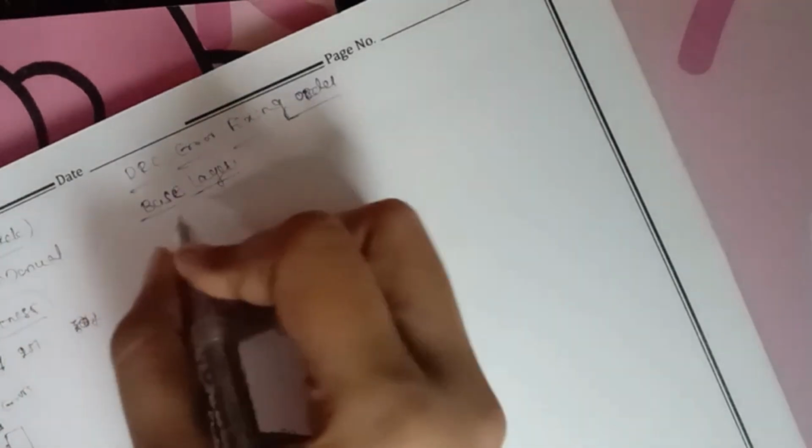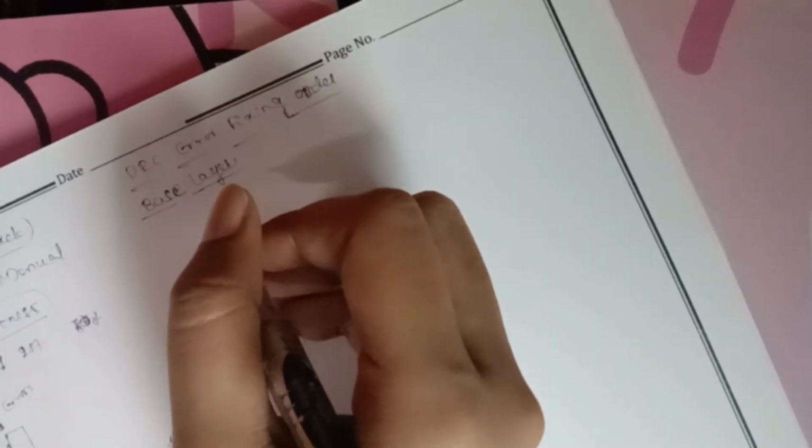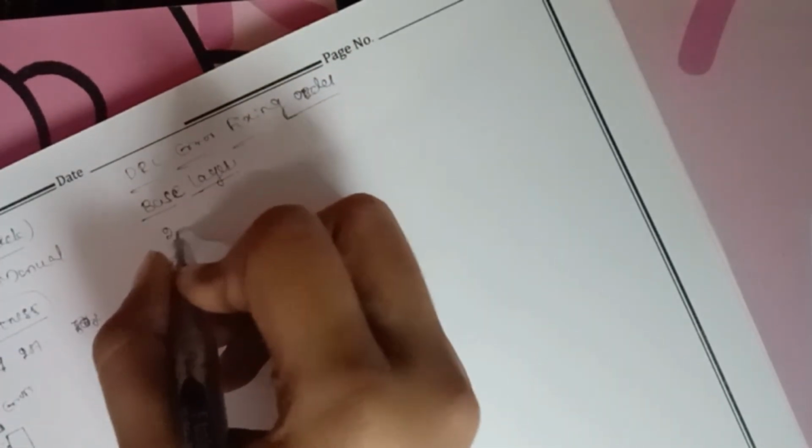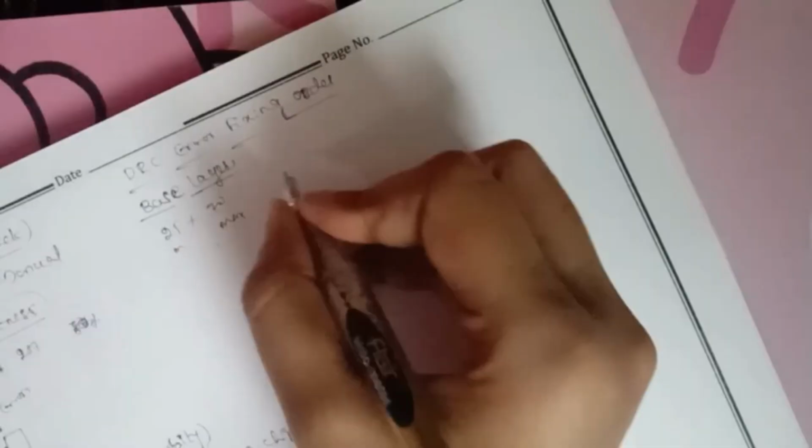So in base layer, what we check for is base density violation. Like I said, density should be around 25% to 70%, minimum and maximum, whatever the DRM rule says. Because for the CMP process, CMP means chemical mechanical planarization, when we do chemical and mechanical polishing, sometimes it will bend in the empty area.